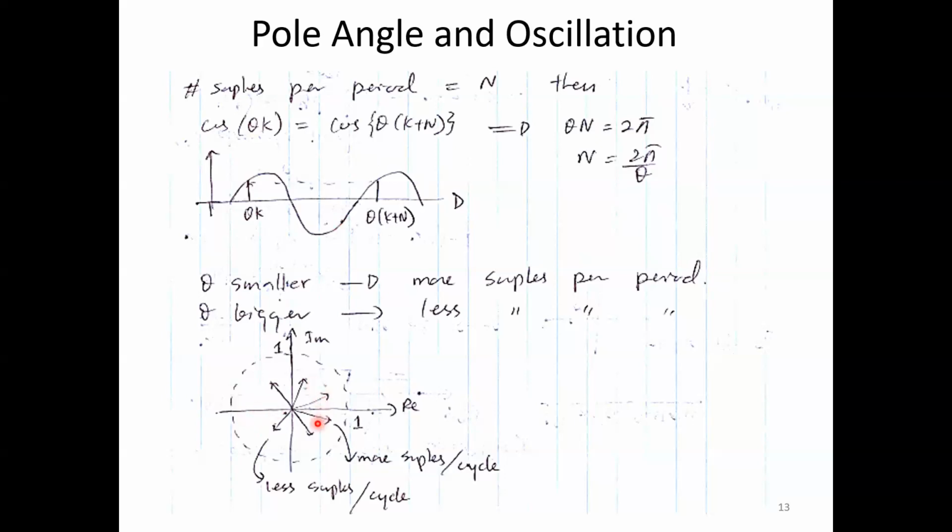But if you get poles over here, positive half plane, right, within the unit circle, then you can safely say, okay, my poles will represent not only the stability, but you also guarantee accuracy of the waveforms. Okay, so you can have a stable system, but not correct. Stability is one thing, accuracy is yet another one. Okay, so please understand that one.